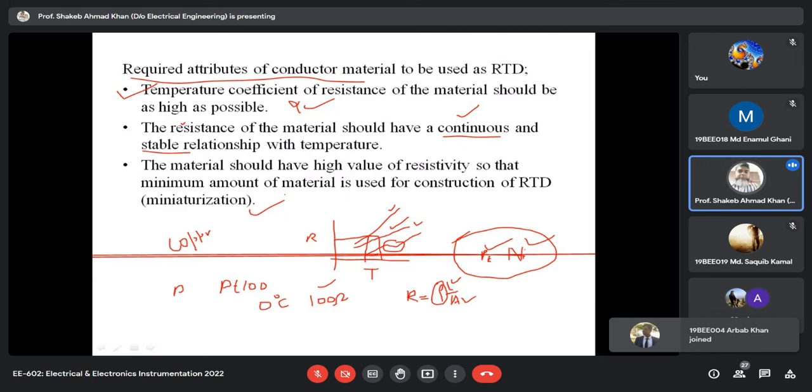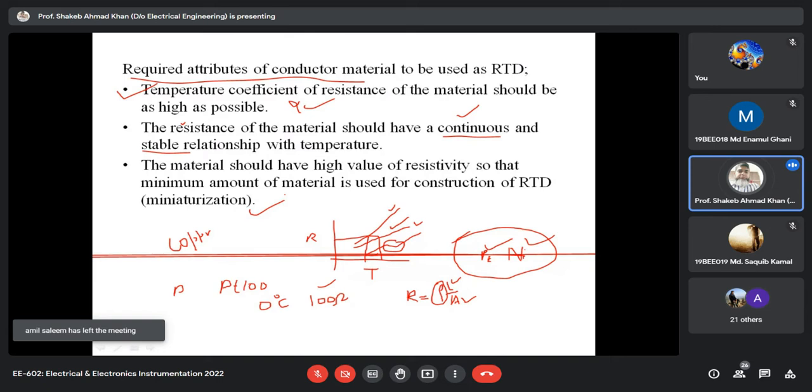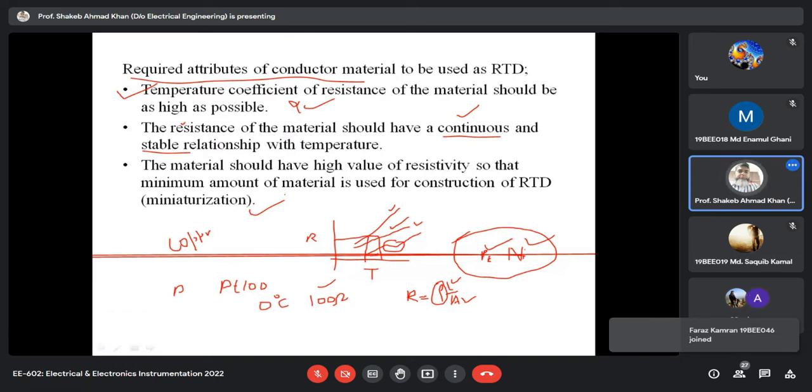In many places, if you are using bigger and bigger probes, there is a time lag with dynamic characteristic, which is not in your course. Basically, it will take more time to absorb the heat and to rise in temperature. And if you have a smaller piece of probe, then its response time will be less, meaning it will work faster.